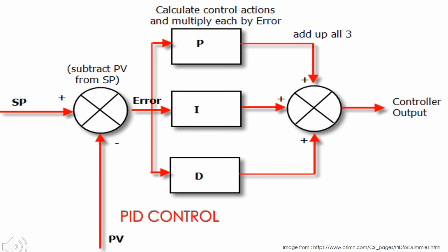The controller then implements the proportional control to return the process variable to the set point. Although using the proportional alone will leave a steady-state error, the integral part tries to reduce this steady-state error. The last portion is the derivative, which tries to reduce overshooting and usually acts against the proportional and integral portion.